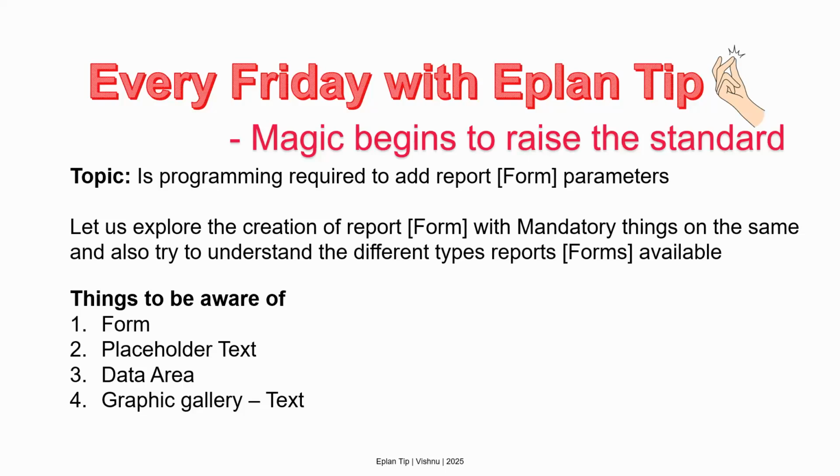It all depends on which group and what property you're looking for. Either you want it from the drawing, the parts, the connections, or the device. All those things will depend, and you go and search for a particular property name and do it. Sometimes you may not get what you're looking for. Don't worry, do some R&D and automatically you will be able to extract it. Some ready-made forms are already available in the Eplan engineering standard. Go there, download them and start utilizing those forms.